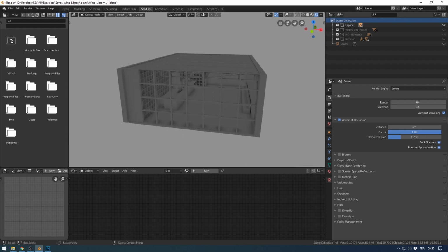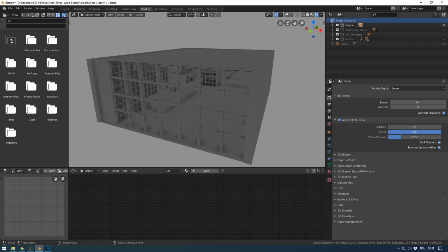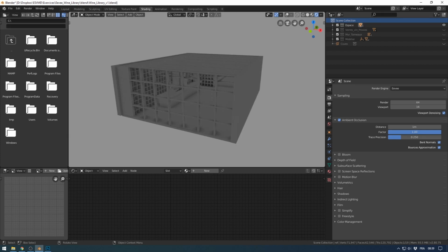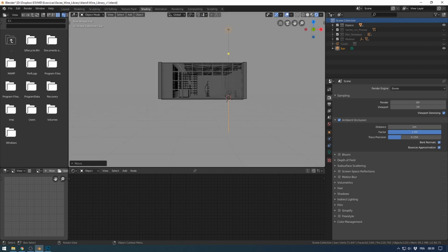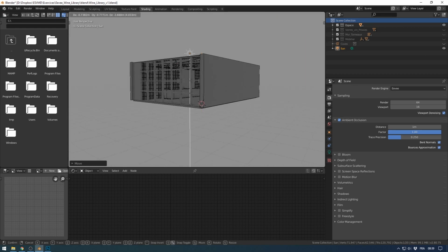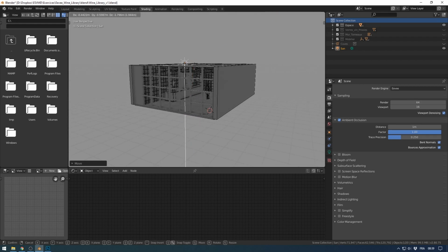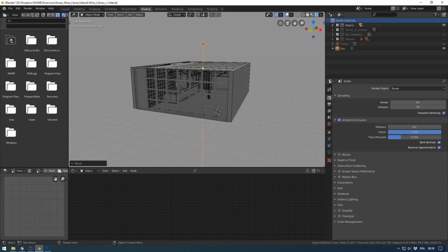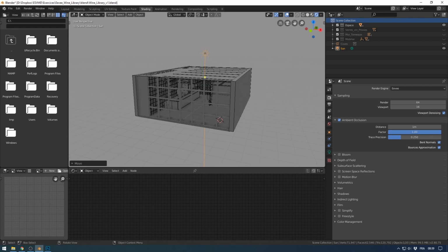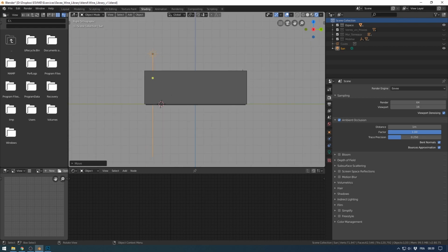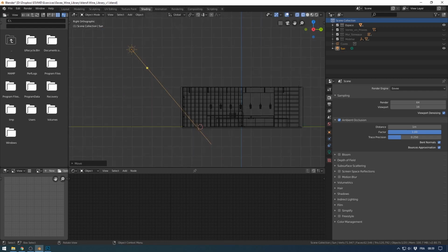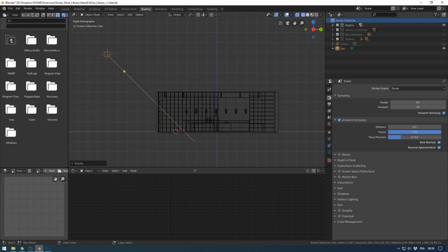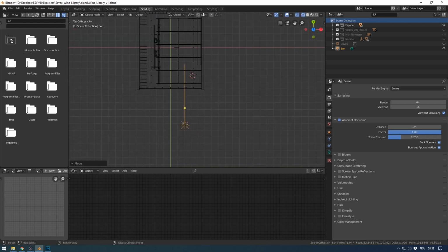The second thing you want to add, usually, is a sun. So you could add a sun here, and the first thing you will see is that in Blender Eevee, the position of the sun is important. It's not a simple directional mass of light coming from one direction. The position of the sun is really important. So you will probably want to set your sun, for this kind of scene, in my case, something like this. And I will just rotate the light a bit like this.